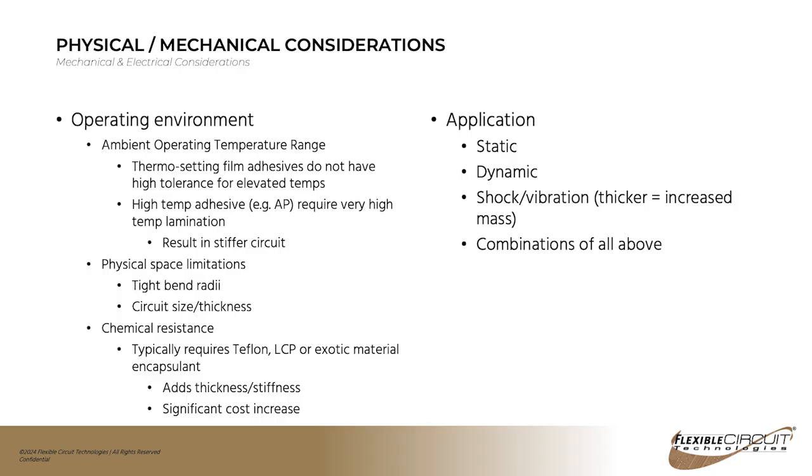And as far as the application, static versus dynamic, when you look at your static applications, are you going to be able to form it the way you want to so that it'll fit? If it's dynamic, it's going to have to be ultra flexible. You're going to have to take into account neutral bend axis and things like that that really don't play nicely with impedance control and other things like that. So those are all going to have to be weighed.